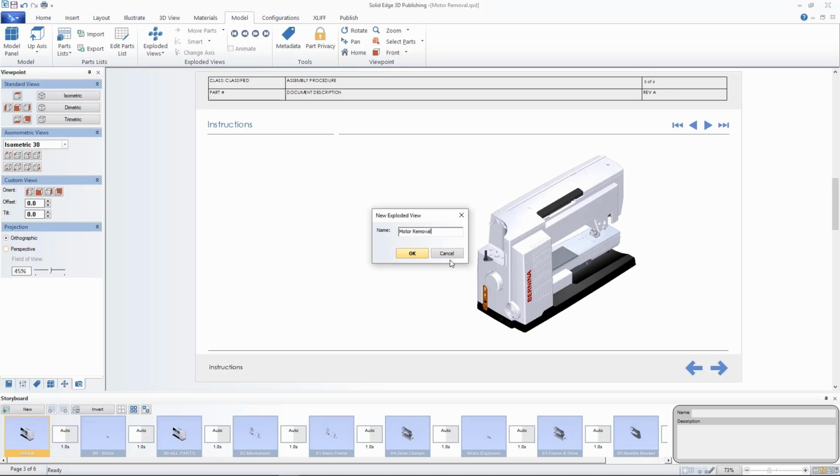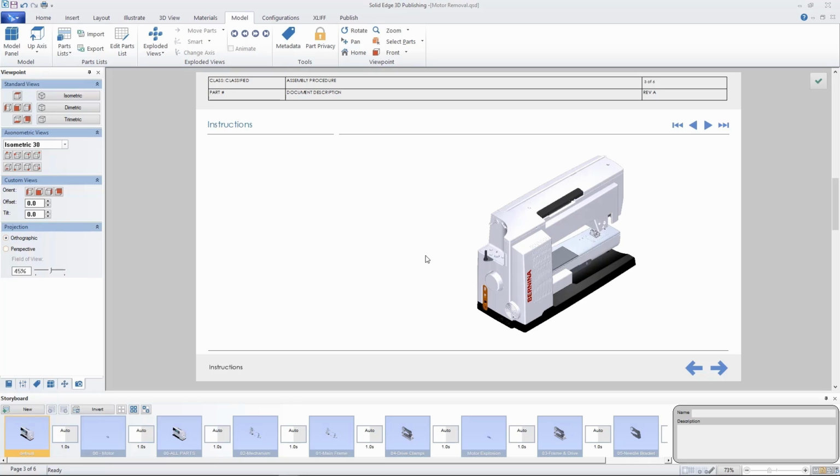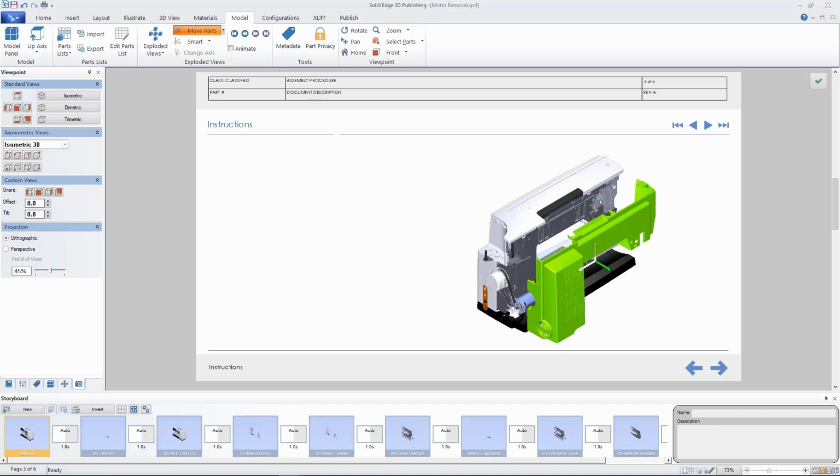There are several options for how you want to move the parts and the direction in which you wish to explode them. Here we use the coordinate system of the part to get access to the XYZ directions and pull each component perpendicularly to how they're placed.